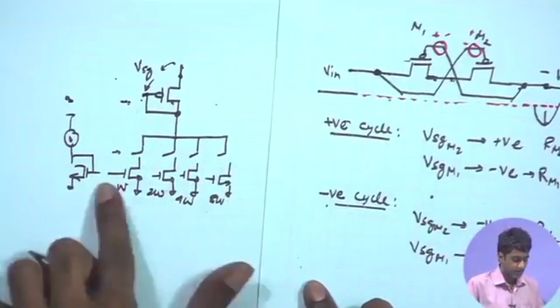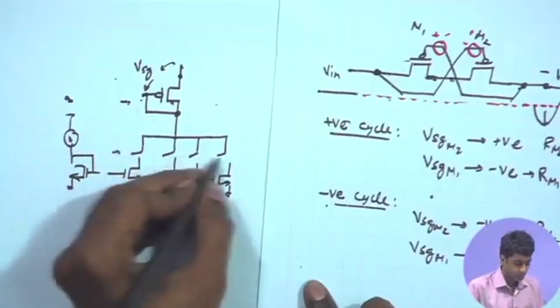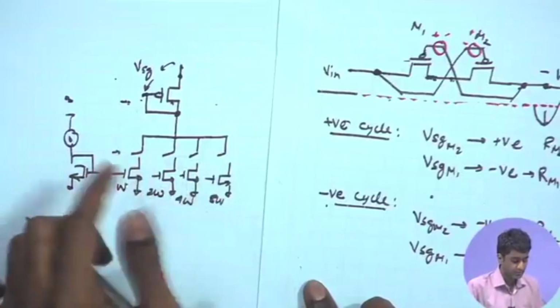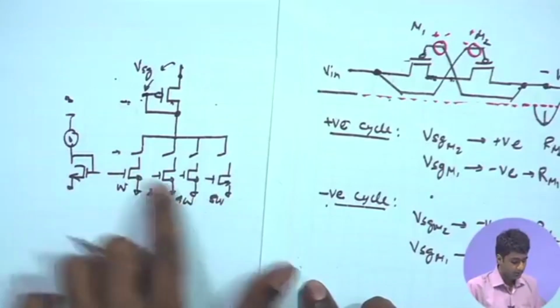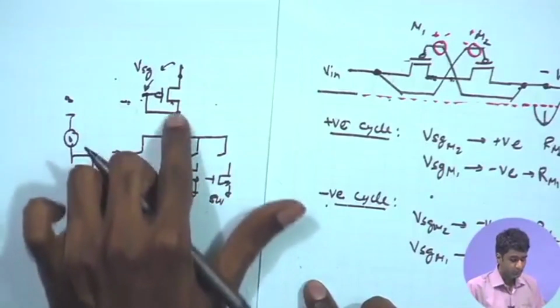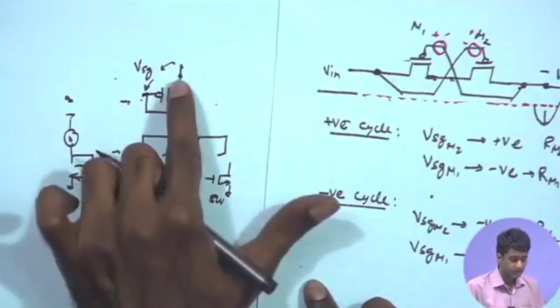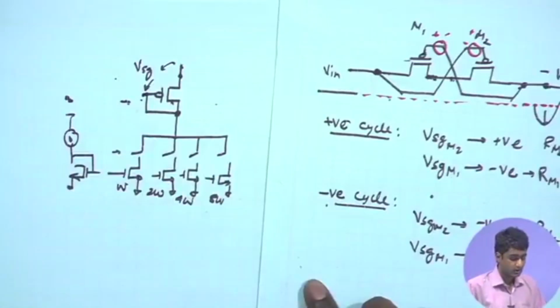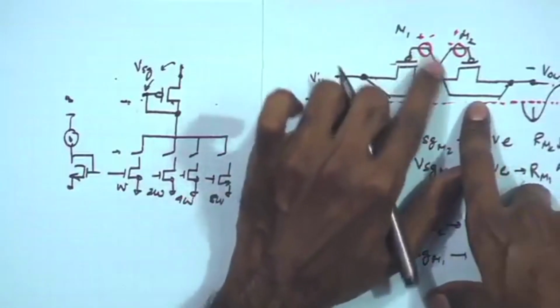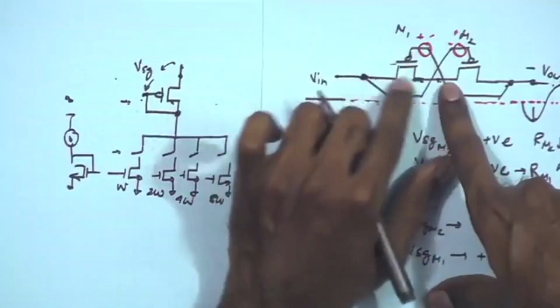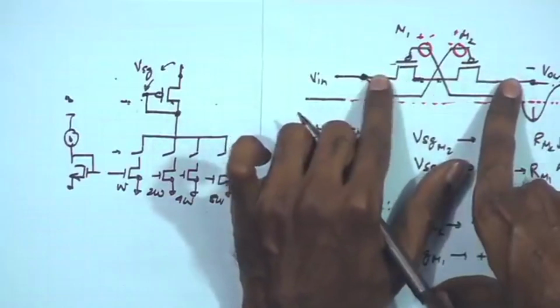So, if you are adjusting these switches, depending upon which switches you are turning on based on a binary 4-bit word, we can control the total amount of current flowing through the PMOS, and as a result the VSG also gets controlled, and hence this logarithmically controlled VSG is going to once again control the resistance almost in a linear fashion.